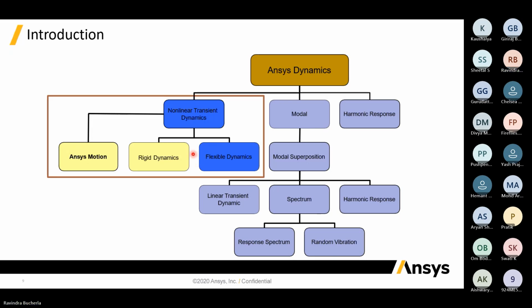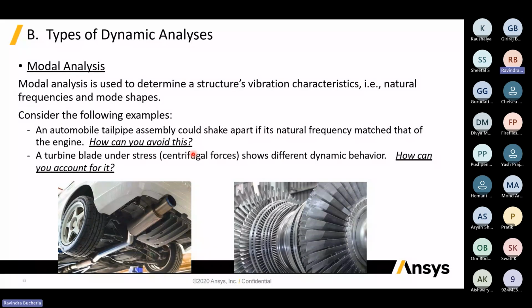Whatever dynamic problems we will be solving, especially when we talk about vibrations, suppose we take any motor or any rotating equipment. One of the major challenges that we face while dealing with vibrations is that if any geometry has external vibration, and that external vibration collides with the natural frequency, there is a high chance that the geometry is going to be in a resonance condition.